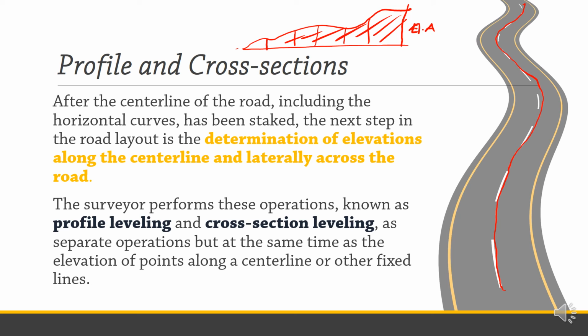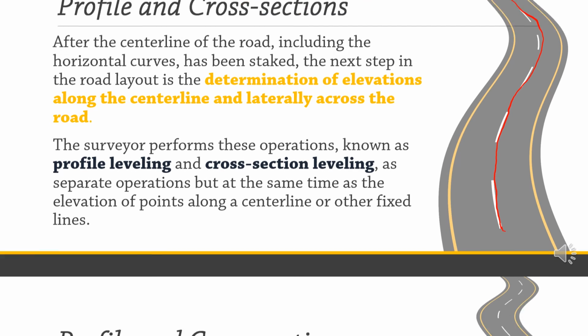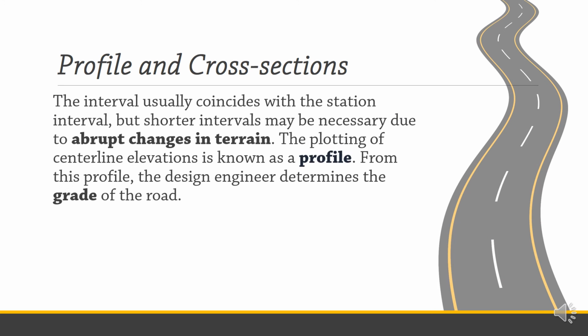So, as separate operations but at the same time as the elevation of points along the center line or other fixed lines, the interval usually coincides with the station interval. But shorter intervals may be necessary due to abrupt changes in terrain. So, say, kung may biglang lumalim na part doon, you'll have to stop there to take an elevation. So, the shorter the interval, the more accurate the profile will be.